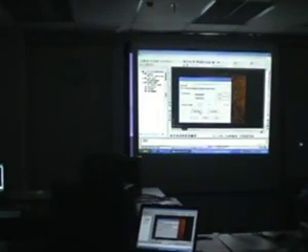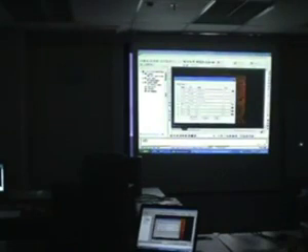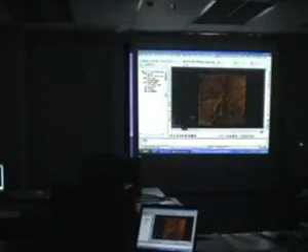The number of ranges is 5, so I want to click auto range. Okay, and what it does is automatically look for the lowest and the highest elevation points, in this case from 22 to 77. It divides this into 5 equal ranges for me, and each range is going to be on a different layer with a different color. So the lowest is between 22 to 33, and they'll be colored red, followed by 33 to 44, yellow, and so on. I'm just going to click OK.